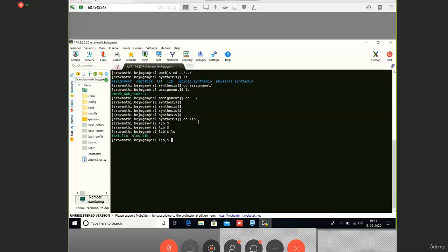I'll discuss in the STA sessions what these two types of library are and in which cases we'll be using them. But as of now, in the run.tcl file, I have given the path that you need to include as slow.lib. You can change the file name to fast.lib also, execute the file and see the changes in the reports of timing, power and area. Open run.tcl, Shravanti. Okay.